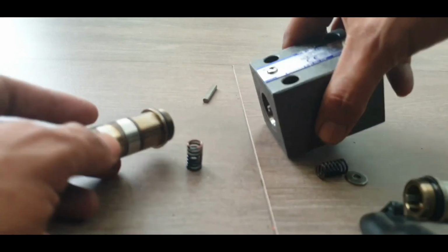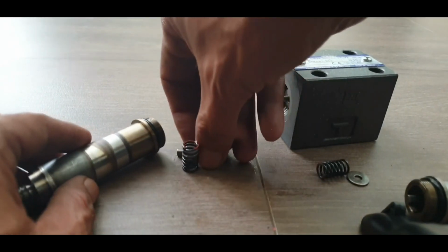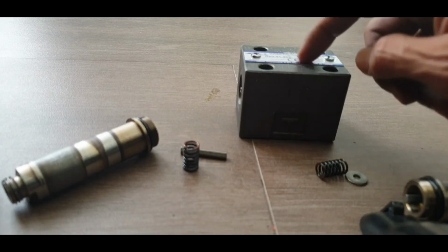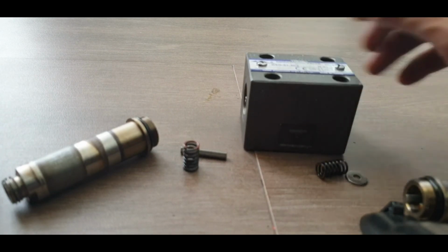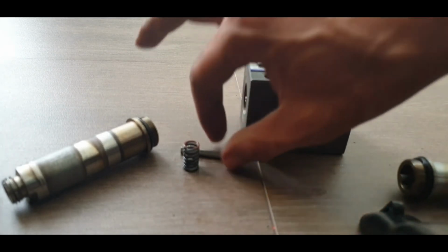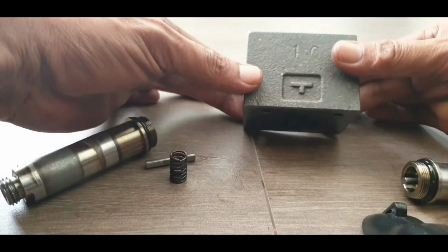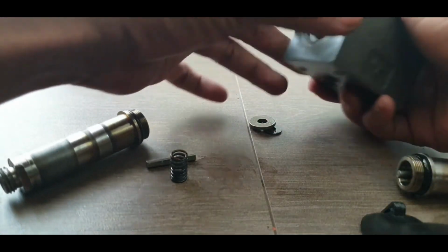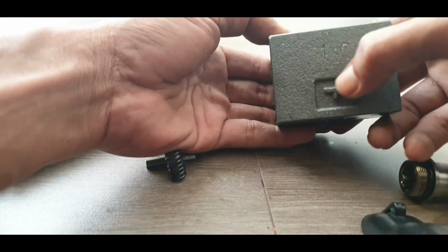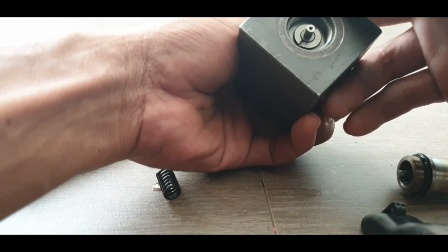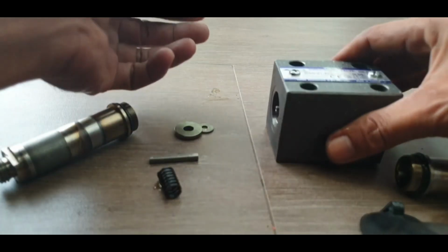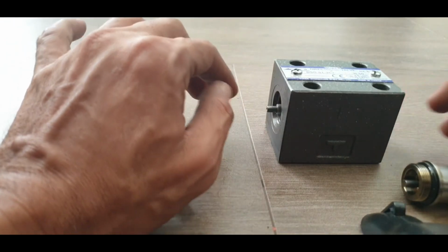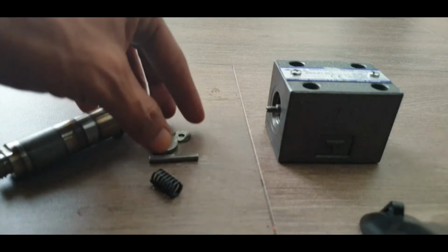Same, it's also a spring and a small plunger here. Okay, now this is the main one, to manipulate the direction of the fluid flow inside. So this is a huge rigid one. Okay, there is no interconnection, it's rigid. So if I push from these directions, there is what we call a spool inside,